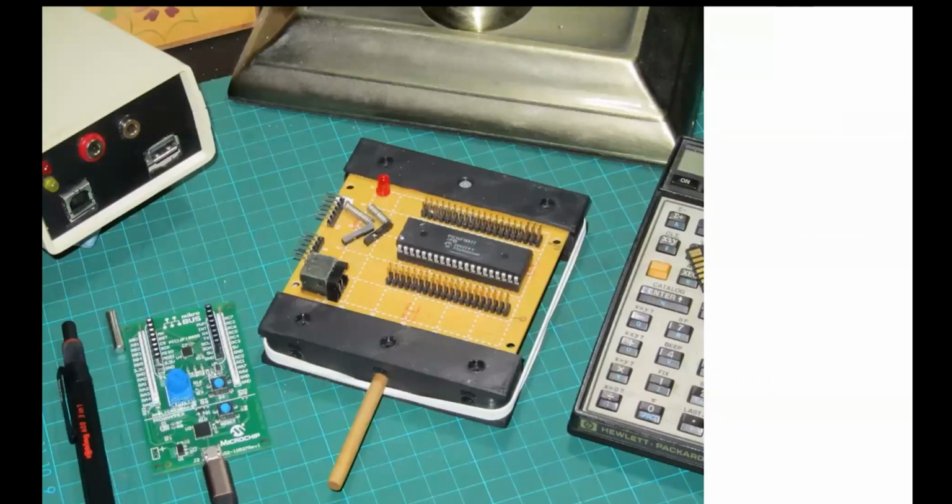There's its big brother there, and that's the 18877. The 18855 and the 18877 are the same chip, all the same peripherals, except the 18877 has 40 pins, and it's available in PDIP, so you can get a meter or a scope probe onto it. And that's a simple wee prototyping board, simply to let me, again, do basic development stuff. You can see my 155 board to the bottom left of that picture, and the slightly bigger one with the 40 pin chip on it.